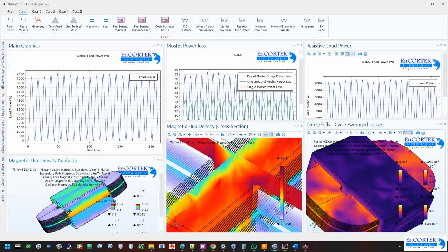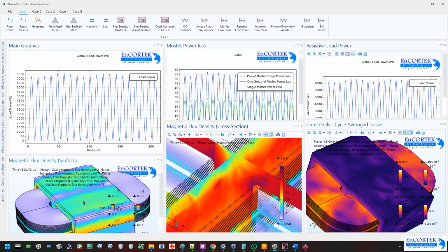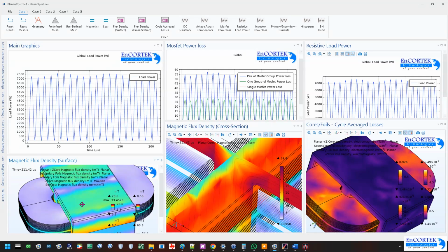The theoretical rating of the transformers in car amplifiers is like 3000 watts peak, and they really try to extract half that, so it would not have instability and spikes which could damage the FETs, and so it wouldn't try to go into saturation itself.